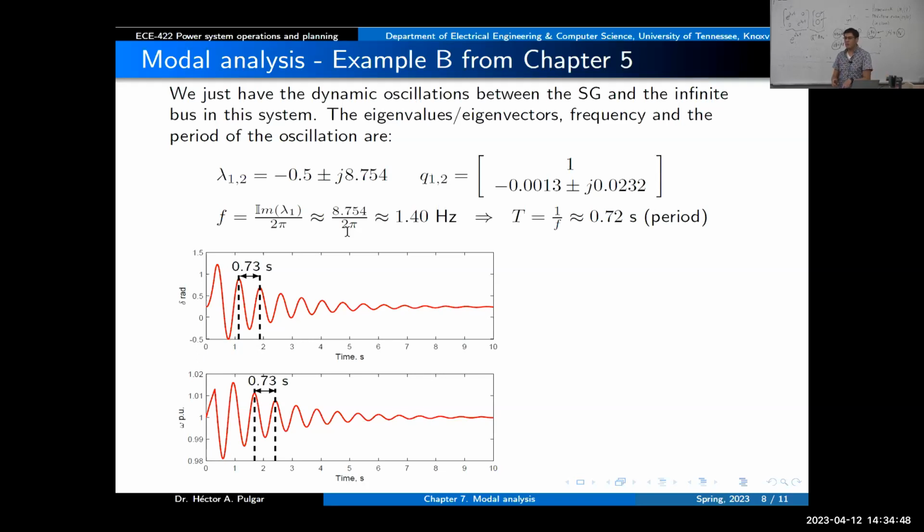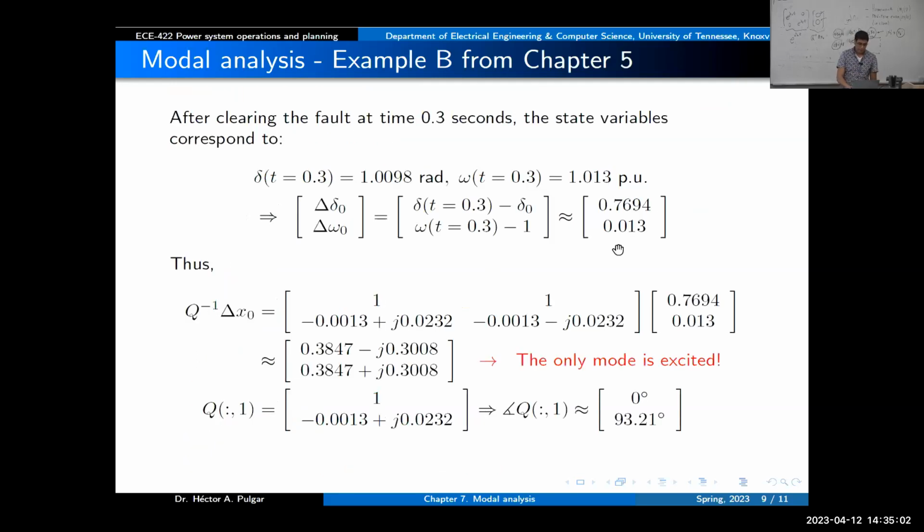And what is the dynamic behavior of that? The machine oscillating with the infinite bus. We just have one mode, basically. And what do you see in the time domain simulation? Just one mode of oscillation. And that is very close to what we determined here.